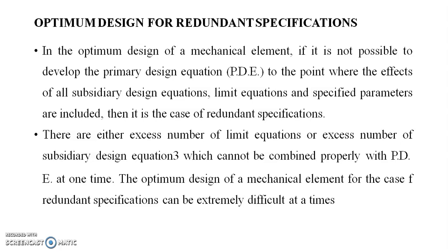Therefore, the optimum design of a mechanical element for the case of a redundant specification can be extremely difficult. So, what is the conclusion in short? In optimum design, when it is not possible to develop the PDE where the effects of all SDE, LE and specified parameters are included, then the case becomes one of redundant specification. There are either an excess number of limiting equations or an excess number of subsidiary equations which cannot be combined properly with the primary design equation at one time. This is a difficult case.